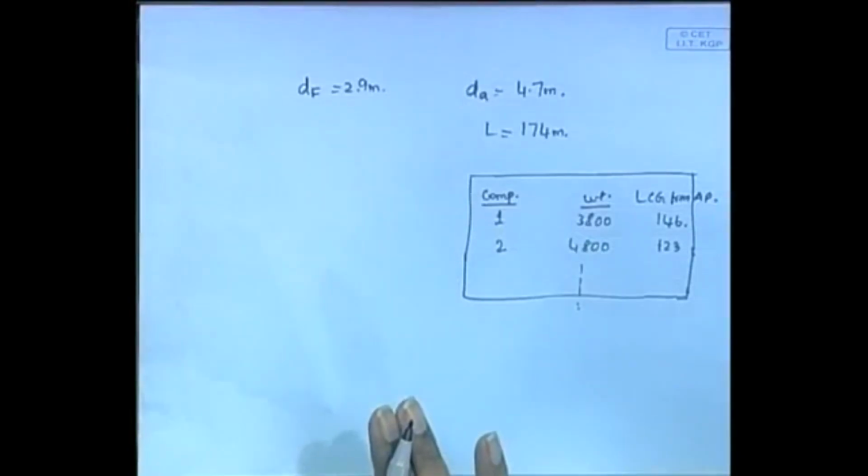Then you are told that the ship is trimmed. That itself says that the buoyancy has shifted from that position. It has shifted to some other point, and it has shifted so much that finally your B is directly above, on, or below the center of gravity. Therefore, you know where the center of gravity is. By working on this, you will get the center of gravity.